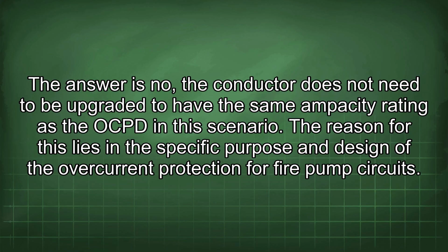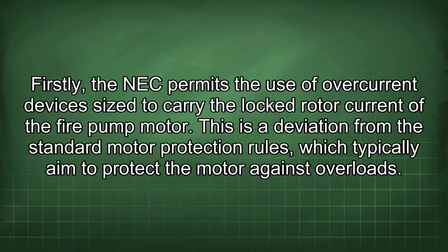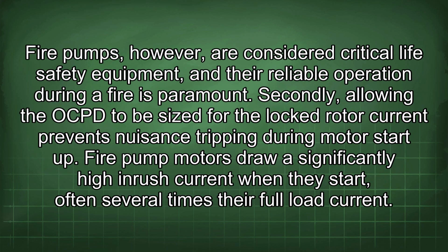Firstly, the NEC permits the use of overcurrent devices sized to carry the locked rotor current of the fire pump motor. This is a deviation from the standard motor protection rules, which typically aim to protect the motor against overloads. Fire pumps, however, are considered critical life safety equipment, and their reliable operation during a fire is paramount.